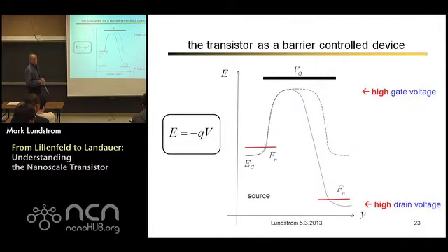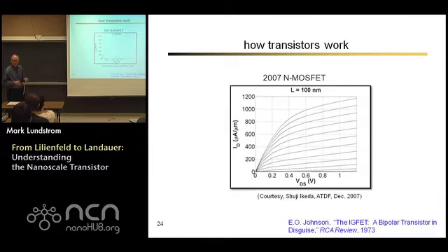So that's really how transistors operate. Sometimes when you do the math for these IV characteristics, you do this charge Cox, Vg minus Vt, you don't appreciate what's actually going on. Where's that charge coming from? It's electrons hopping over the barrier, getting in the channel. That's where that charge is coming from.